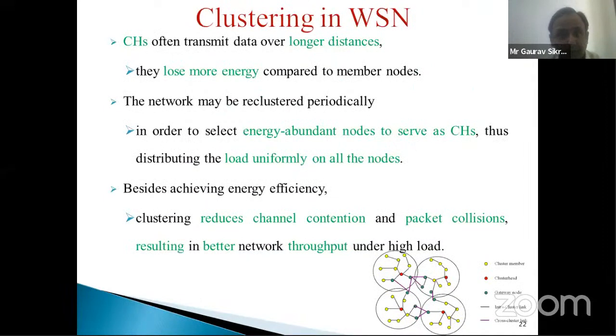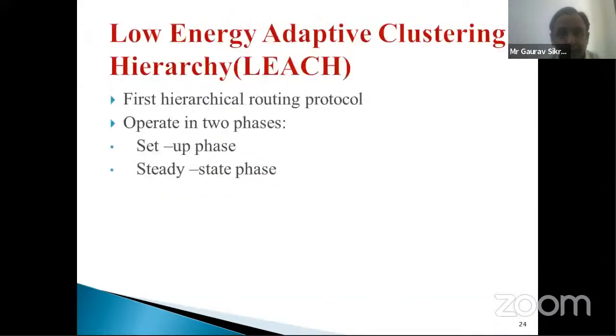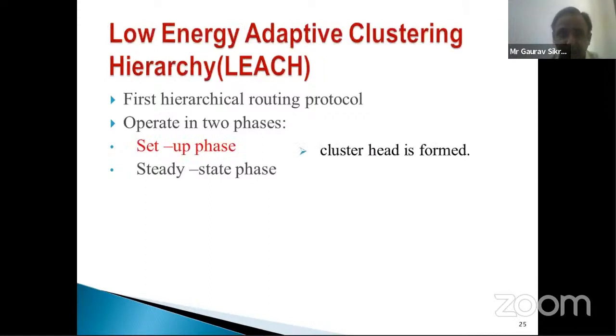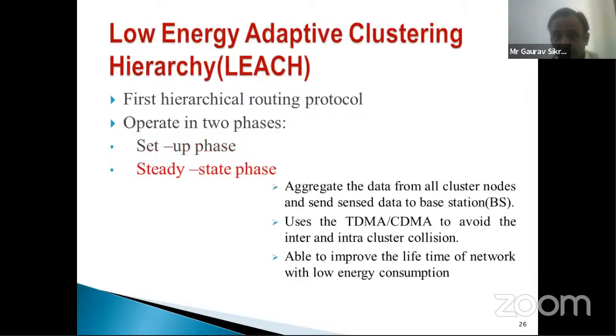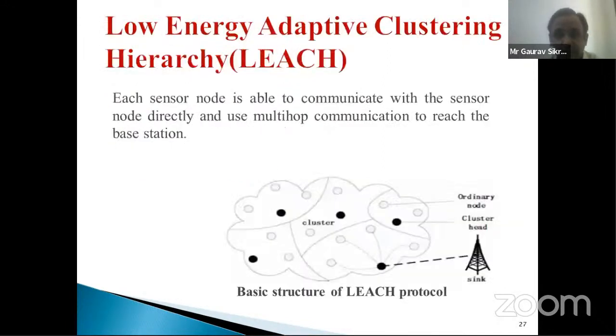In clustering, the main approach used in our paper is the LEACH approach. It is the first hierarchical routing protocol, and operates in two phases, the setup phase and the steady state phase, where the cluster head is formed, and then that cluster head transfers the data to the base station. It uses TDMA and CDMA approaches. The LEACH approach is discussed in this particular diagram.